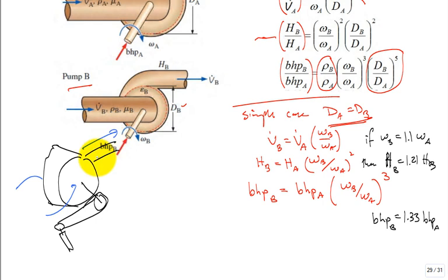And then the new engineer, the young engineer, new job, undersizes that blower. He undersizes the fan. And he needs to increase the volumetric flow rate right there. And he says, ha-ha, I learned in fluid mechanics that if I make it spin faster, then I can get more flow out. So he tells the mechanical contractor, change the diameter of one of these pulleys, and I'm going to tell you what to switch it out.